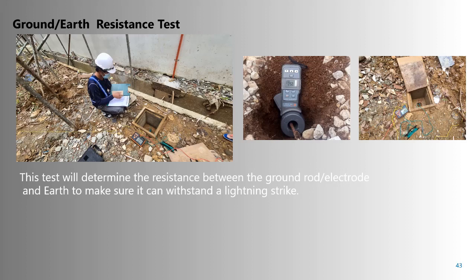So that's the maximum value you could go, as per code. But in my experience doing lightning protection using a triad design, that's a triad grounding system, I preferred that because I get much smaller values there. So I get 0.5, like in the image, 0.5, 0.8, which is lesser than the allowable 5 ohm. So that's why I recommend triad for the lightning protection system.